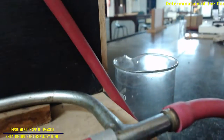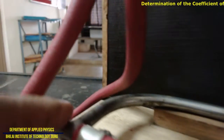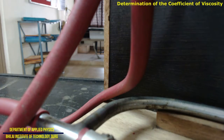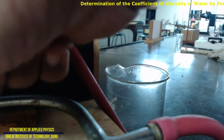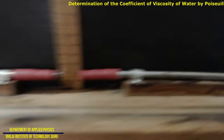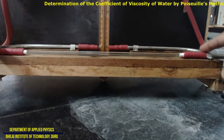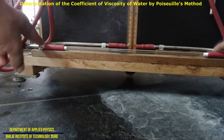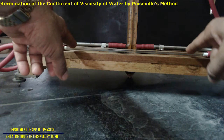Okay, so now the pressure applied at this point is distributed to the capillary tube as well as the first manometer. The pressure at this point is distributed to the output as well as the manometer. So the pressure difference applied across these two terminals is basically applied between the two ends of this capillary tube.